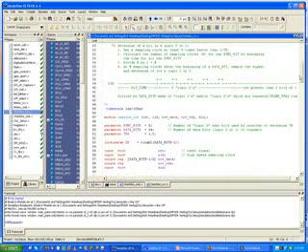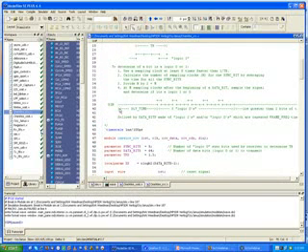Okay, so in this particular receiver, now we know that the transmitter is going to delay a certain amount of time, then it's going to send 5 sync bits, which are logic zeros, what I call a logic zero. In other words, you have the rising edge, a pulse here, which is a quarter of the cycle, then 2 cycles are low, and then of course your low cycle for the last quarter.